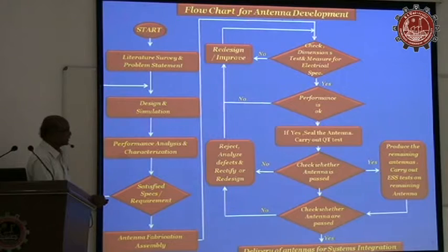and go for qualification test, because these antennas have to be used on a platform. So it has to meet all the environmental specifications. Then we go for qualification tests like high temperature, low temperature, vibration, then salt, depending on the application. If it is shipborne, the salt current is a very important parameter. So we go for that.